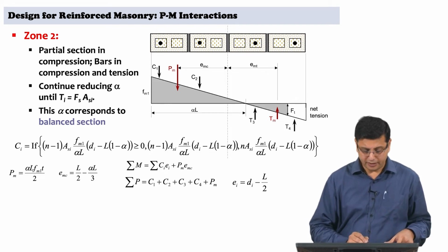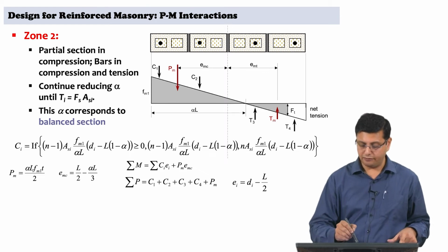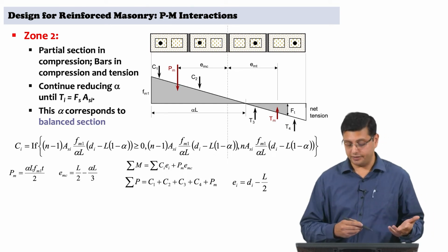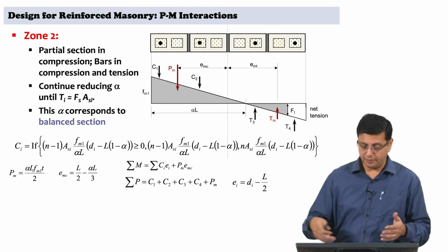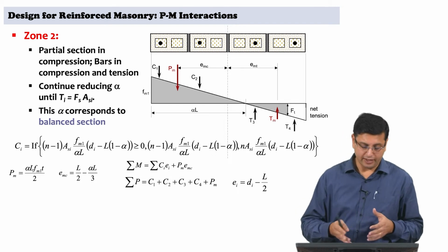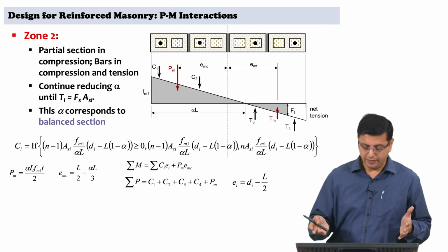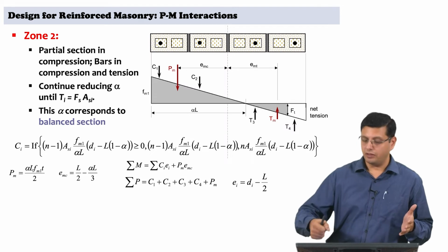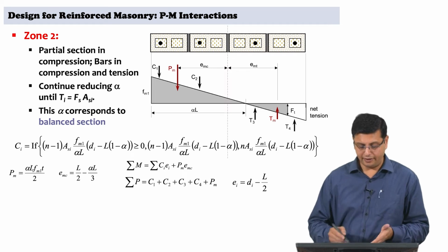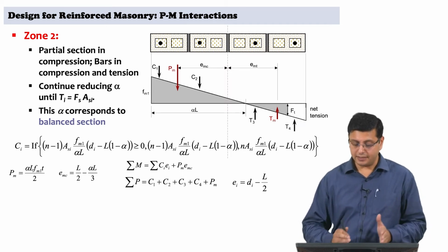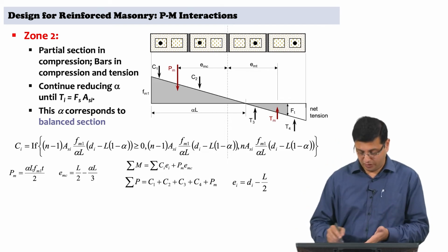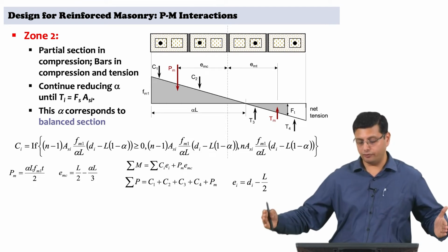So, we are trying to check if C, the compressive force resultant at each bar, is non-zero, positive or negative. As far as the notation and the calculations here, positive is considered to be compression, and a negative value of the resultant force would be tension. So, you need to make that check, and if you are looking at a bar still sitting in the compression side, you will continue to use the previous expression, derivation of the previous expression, because now you do not have the full length.